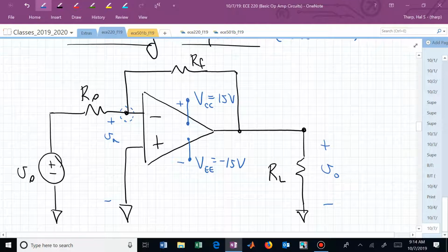And I also have this polarity, which is V sub p. Now, if I'm assuming ideal op-amp behavior with negative feedback, I can say I have that input voltage constraint. But before I do that, let's look at KCL at that node. If I say this is I sub s, this is I sub n, and this, let's just say, is I sub f.